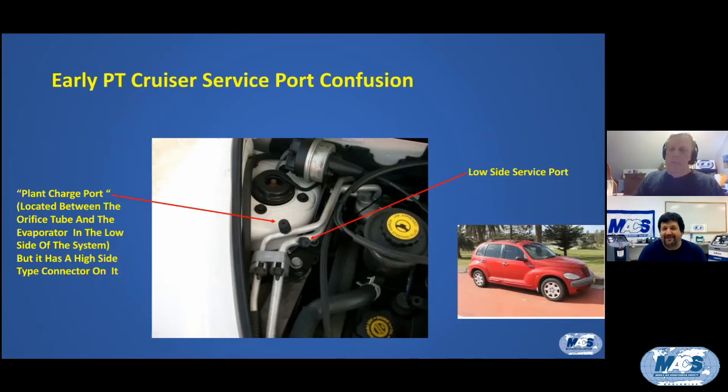So, wow. Really? Yes, sir. And I can't tell you how many situations I've run into where compressors and a lot of components have been replaced unnecessarily because of this. PT Cruisers have a lot of problems with cooling fans. Sometimes the cooling fan won't run at all. Sometimes they'll only run on low. So what happens is you'll have a Cruiser come into a shop.